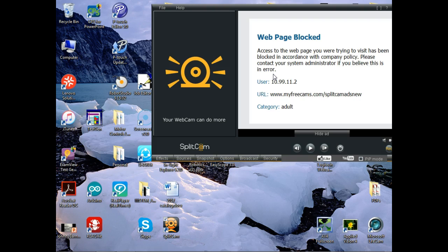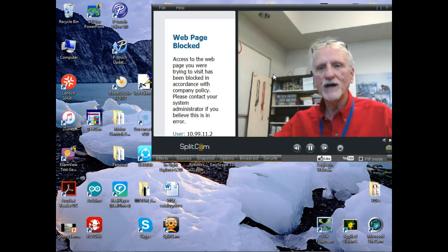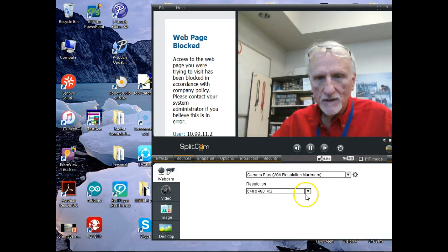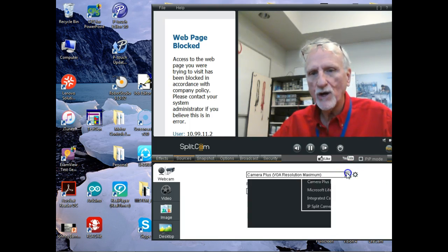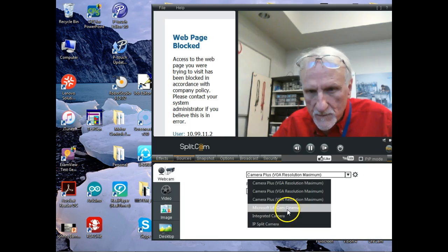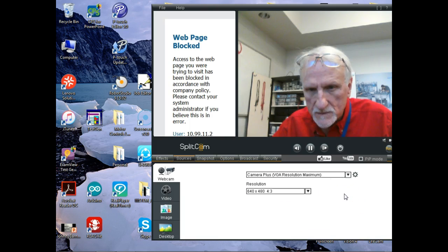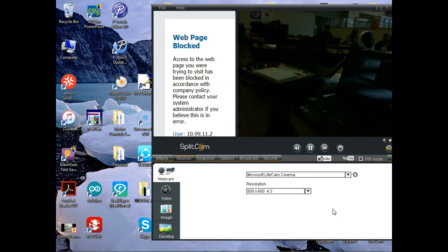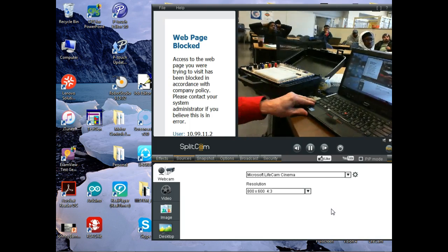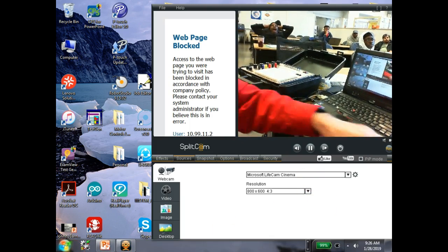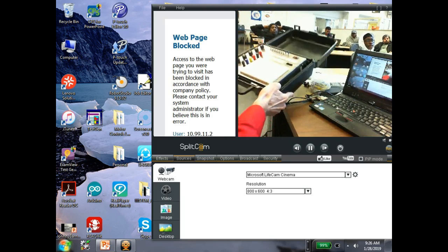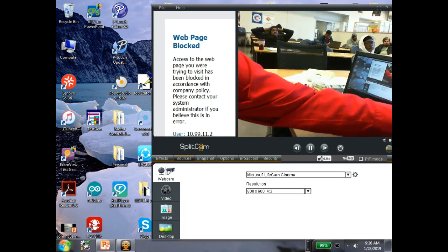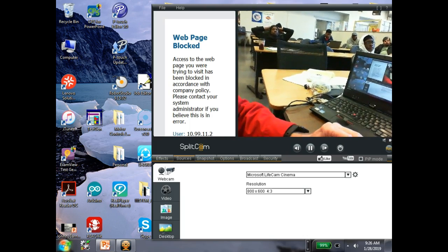So what do you think the red and the black is used for? It's used to power up the logic probe. So these guys don't have batteries in them. They power up off the circuit themselves. So these guys here run off +5. Well, they run off different voltages, but we're going to be dealing with TTL. So the first thing that we need to do is switch the thing over to TTL.